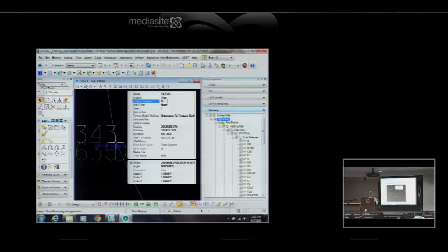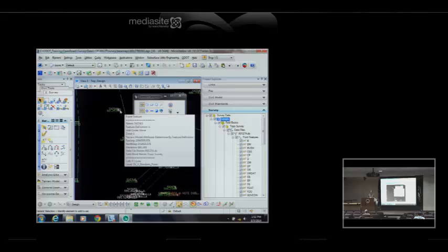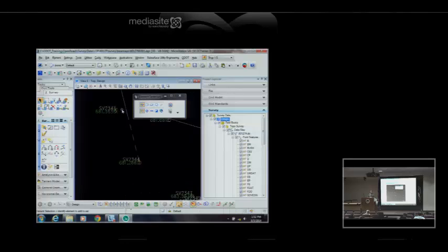And because this is a dynamic link linear feature, it says, oh, X is not the same field code, so I'm not going to include it. So it dynamically readjusted that chain. I haven't answered your question yet, I'm getting there. So that's the second feature type, a dynamic link linear feature. They all have to be the same code, and they're connected in the order that they're shot.